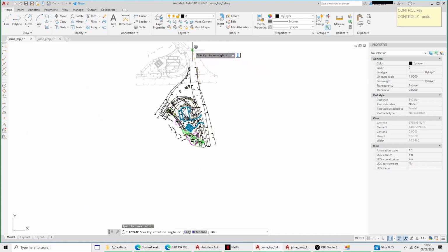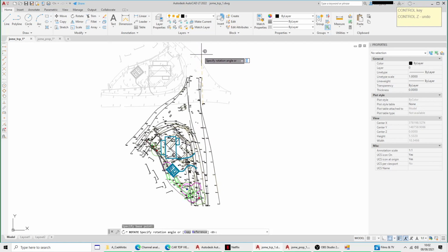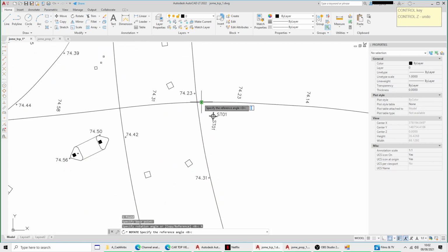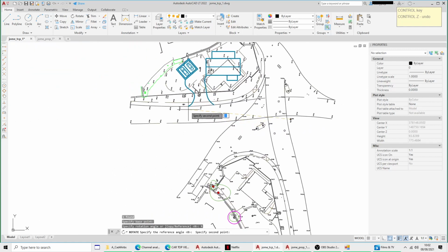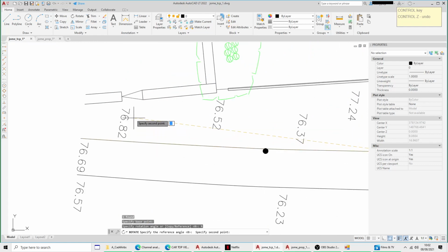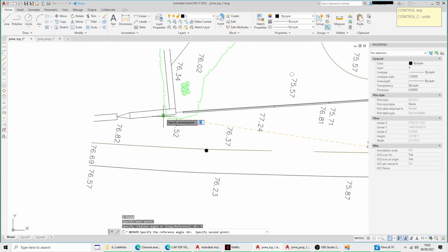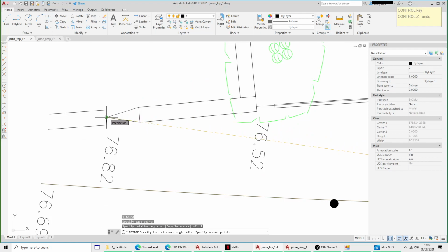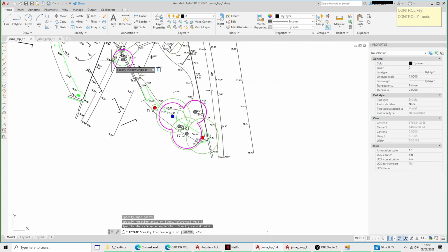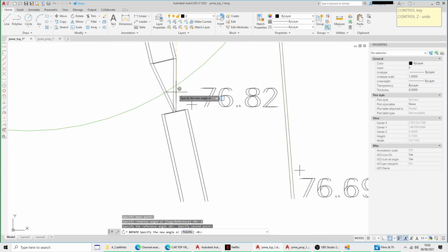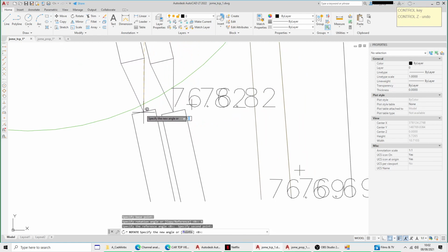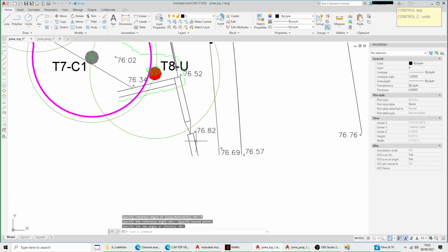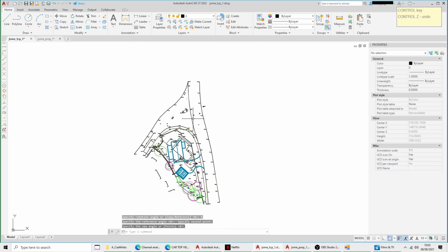You can't do it by freestyle, you won't get that accurate enough. So you've got to use the reference, and you pick the source, reference, position by selecting something else on both drawings, like this, whatever it is, bit of a gate, I don't know, and then pick the same location on the other drawing, which is there, because I'm locked onto this, so I'm just going to lock it onto the same one there, and they're both perfectly aligned.